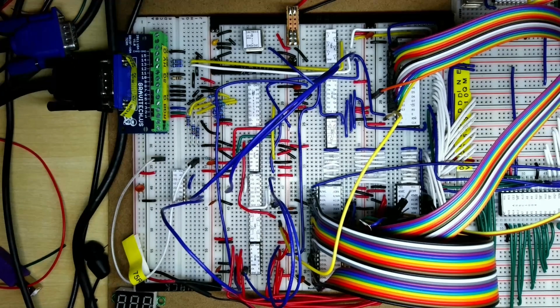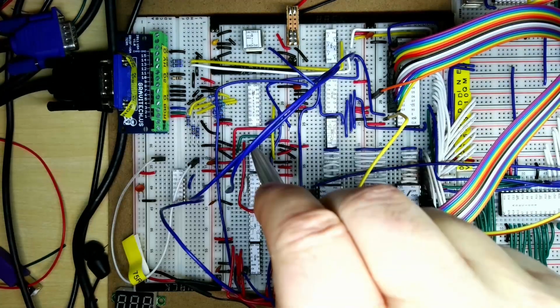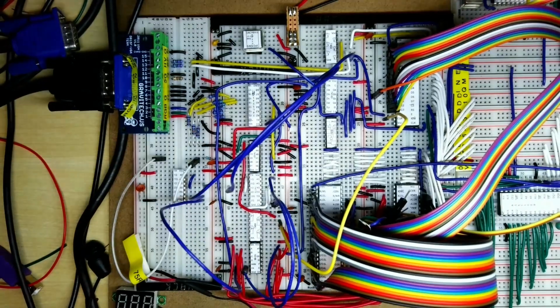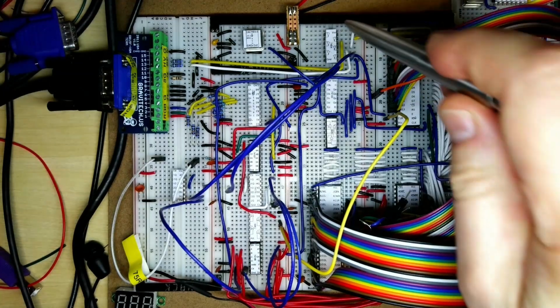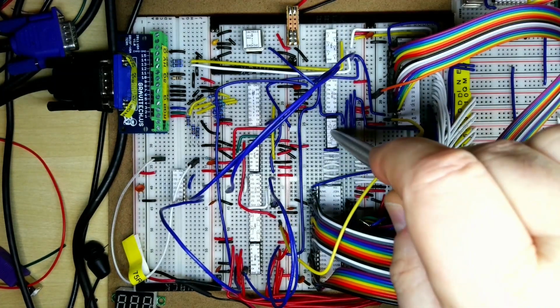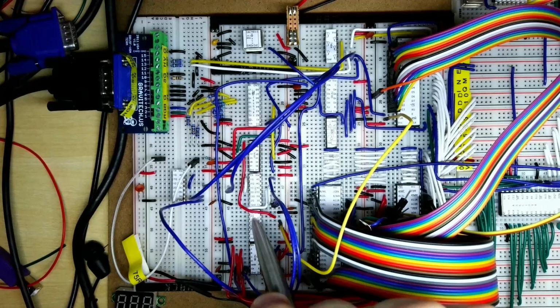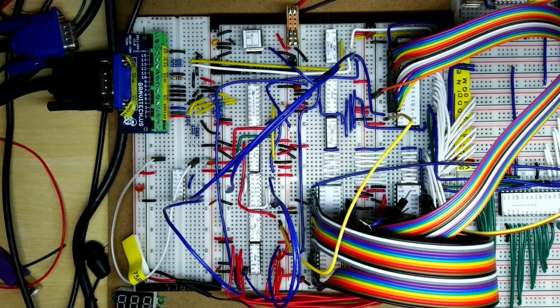So if we have a look at the top-down layout, you can see here that if we wanted to add a register and feed the buffer here, we're going to have to move stuff down here and do quite a lot of things around. Now, in fact, what I'm planning to do in the next video is to replace this chip, this chip, this chip, this chip, this chip, and this chip, all with one 24-pin PLD, a programmable logic device. I've worked out that I can probably get virtually all of the functions of these different chips into one PLD. So I'm planning to do that in the next video along with all the video RAM changes. That's going to clear up quite a lot of space on the board. So for now, that's what I'm planning to do.